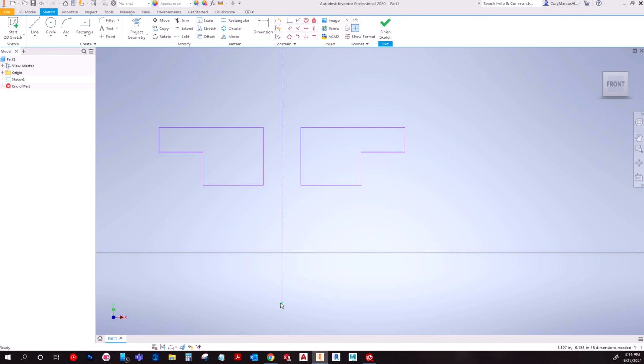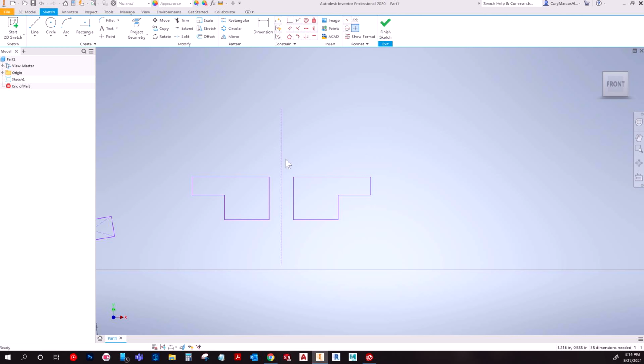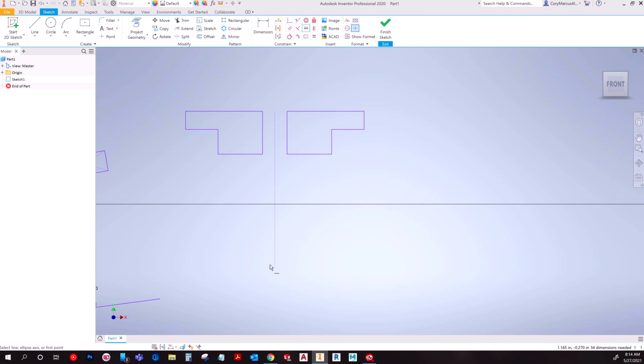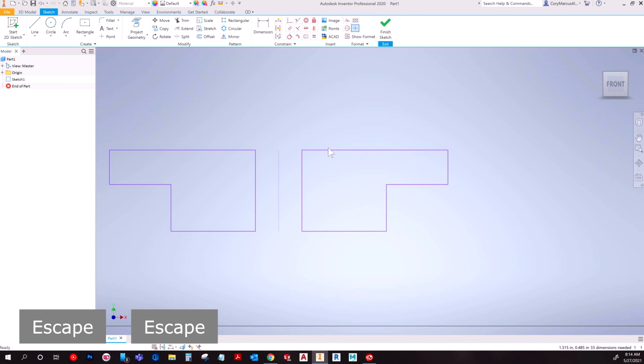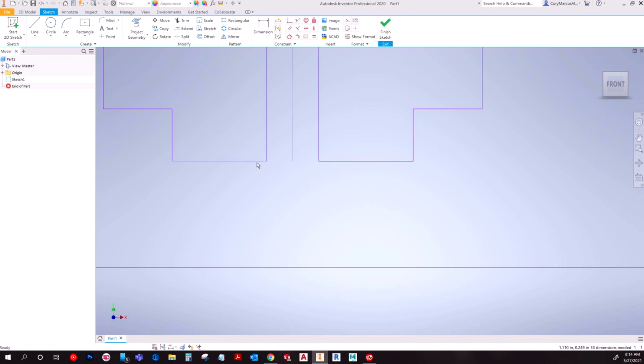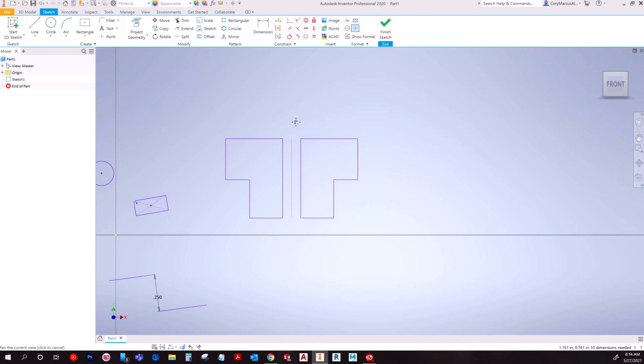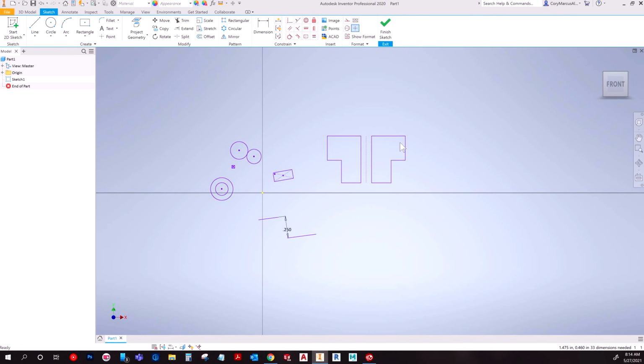But obviously, the one thing I will say, although this is out in space, you would want this line to be sized. So what I usually do, because I'm petty, is I will use a horizontal constraint and just make it the same size as the profile, because that way you don't have to worry about giving it a dimension. It's pretty basic, but just a simple horizontal here makes that line shared with this. So if I grow this, it grows too. I think it's a cleaner look, of course, but it all depends what you're going for. And yeah, that's pretty much it for that one.